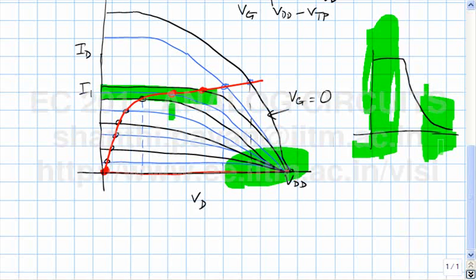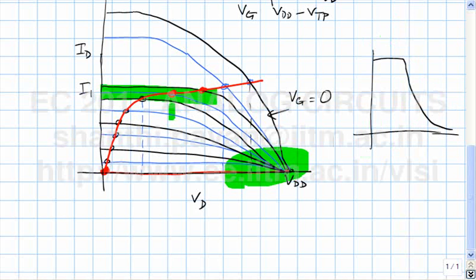As far as analog designers are concerned, the flat portions are totally useless, okay, because they can't give you any gain. What we want is the sloping region. Digital guys get very nervous if things start operating in no man's land. Rule of life, which is any inverting amplifier can be operated as a NOT gate. You understand?